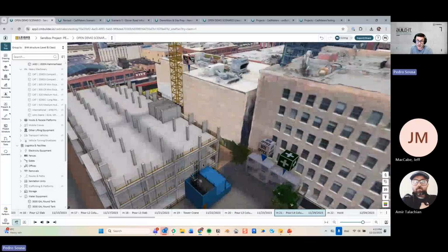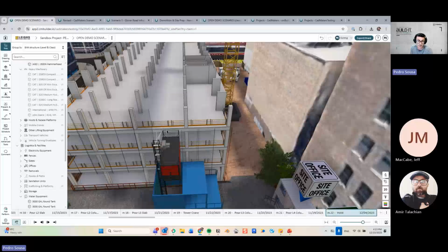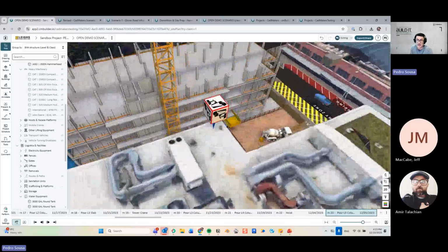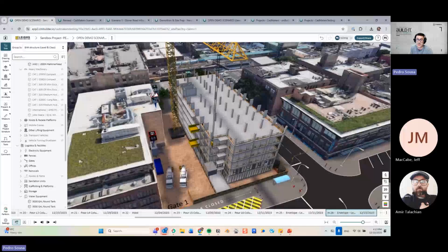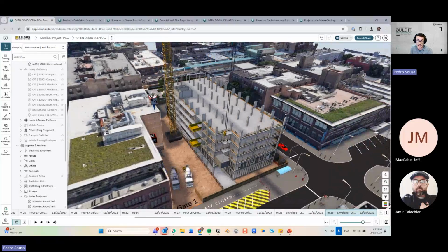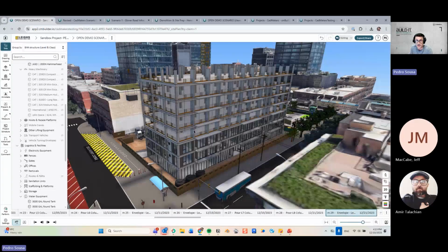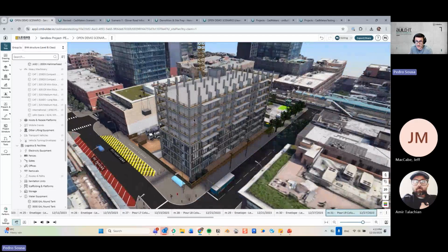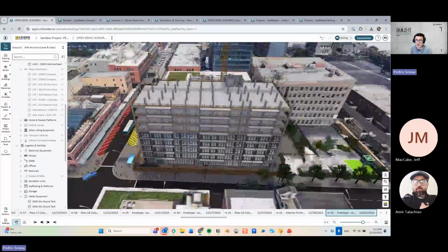So as we keep navigating through this, we're gonna see the different steps of construction, like the placement of a hoist, where that hoist is located, which areas I need to keep open for the hoist access, like when I'm gonna be placing some material, loading platforms, right? How far behind my facade is compared to my live deck, so it can show all of those elements in there, and all of this connected to my timeline.